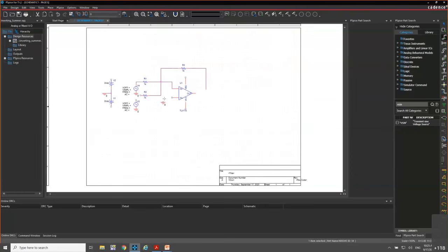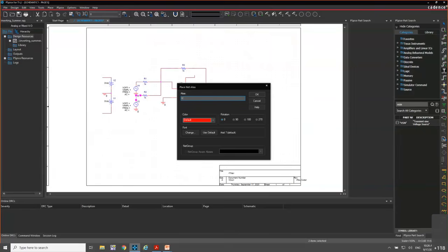And then I'm going to add some extra wires onto the pins for VCC, VEE, and to the top of these sources as well. This is so that when we go to set net aliases, you can't set those to a pin, you have to set those to a wire. So now doing that, I'm going to label the output Vout.